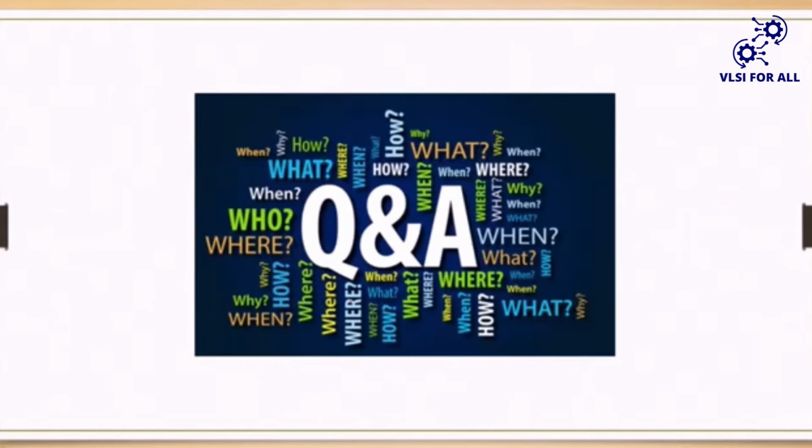Now coming to the sanity checks, what can you check? If it is synthesis, you get the input from the RTL team, which is the RTL code. Whether the code is in the correct form, whether it is bug free or error free, is important to you. If you get a wrong design and you are doing synthesis, it is a waste of time. So you need to check whether you get the right design or not.